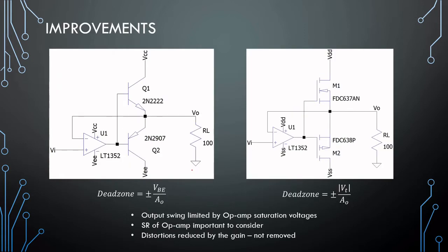Right, now we can improve our amplifier by putting it in the feedback of an op amp. So this op amp is in a buffer configuration. The output here is going to the input, and the input is going into these transistors. By the way, this is how you increase the output current of any operational amplifier. If it can't supply enough current, you can add transistors here on the output.